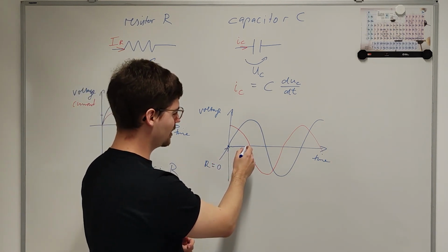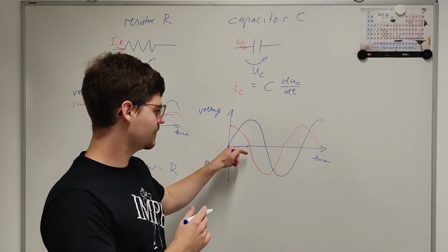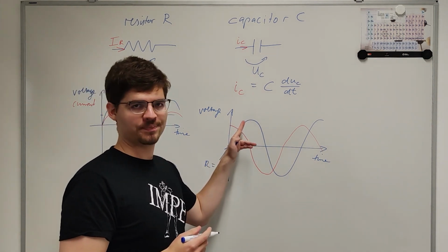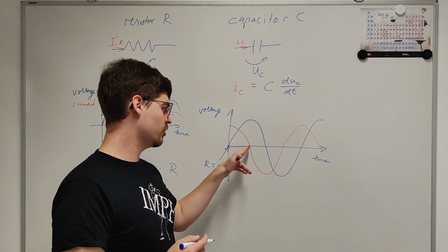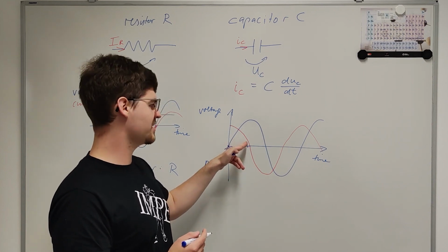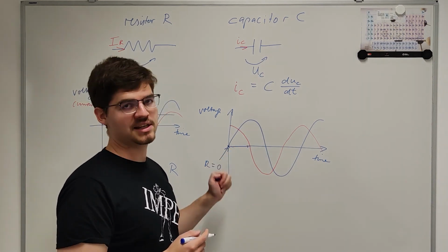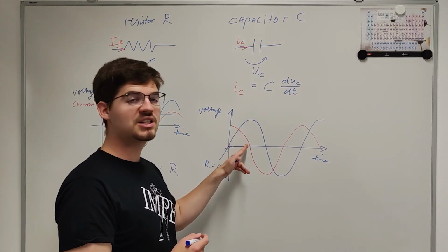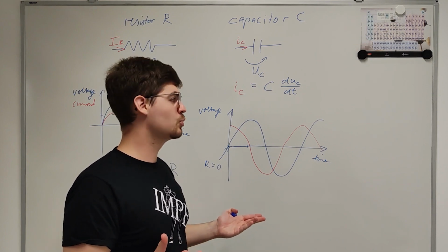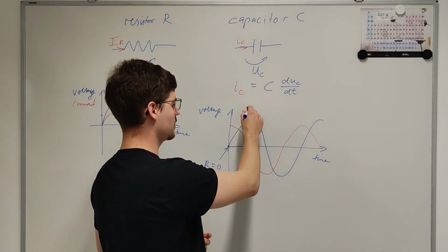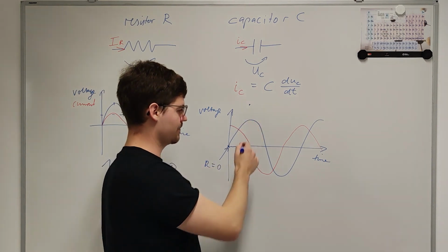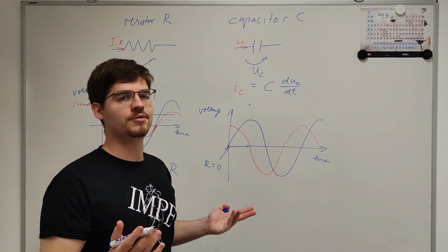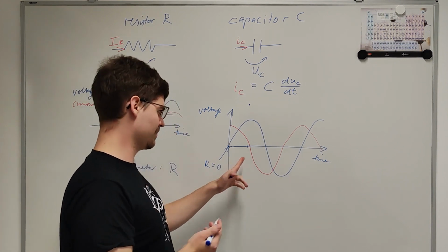Now, let us look very close to where the current tends towards 0. What we have is the voltage near its maximum. But the current goes towards 0. At this point, before it reaches 0, it's still positive and increasingly small. What happens? We divide a very large quantity by an increasingly small quantity. So this quotient tends towards infinity. So it goes here. And of course, this point where I equals 0, this parameter is non-defined, because division by 0 has to be excluded.